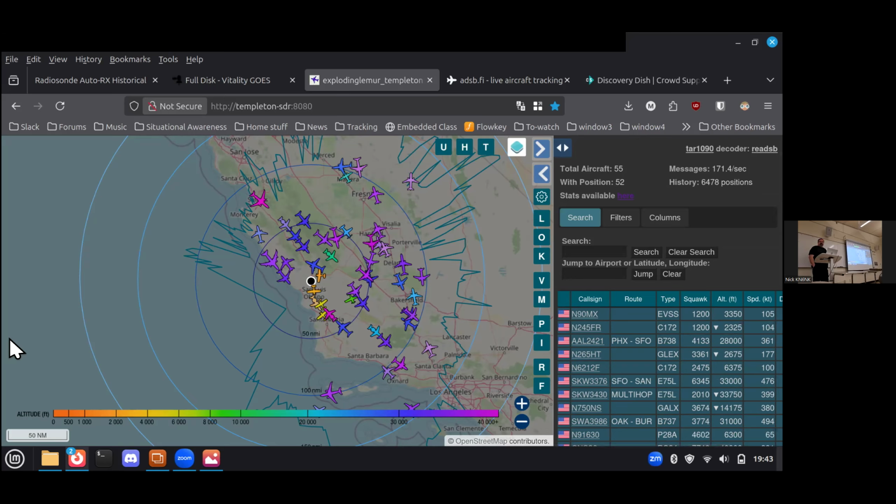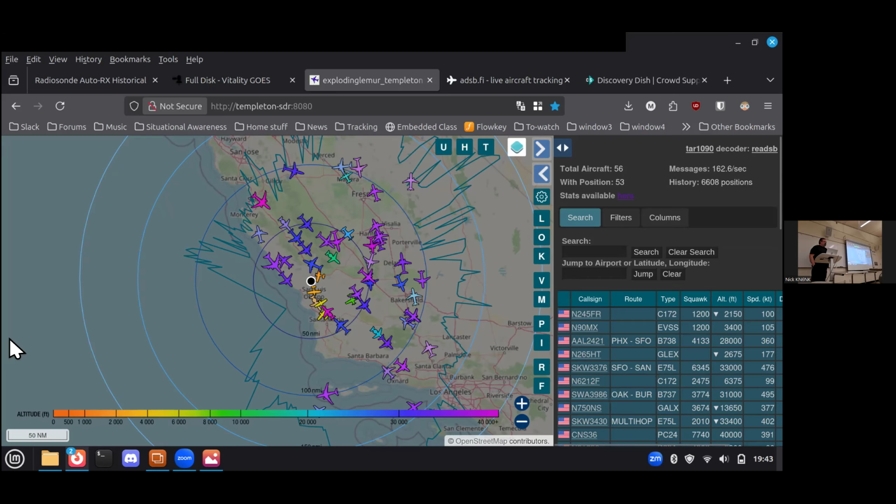There are tiny little portable ones for small planes. If you wanted to transmit ADS-B yourself, would you have to add something? I'd have to add a transmitter. These are just all SDR receivers only. Is that another antenna? Yeah, it would have to be. I could put a transmit-receive switch on one of the antennas, but then all of my SDRs would not be able to hear anything while I was transmitting.